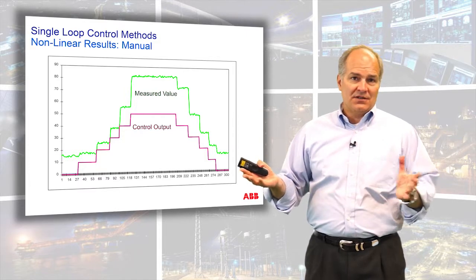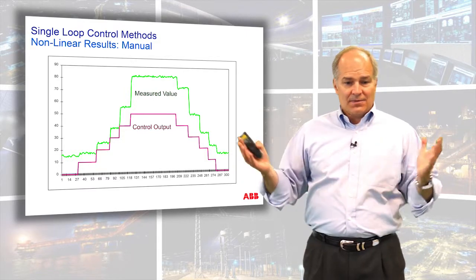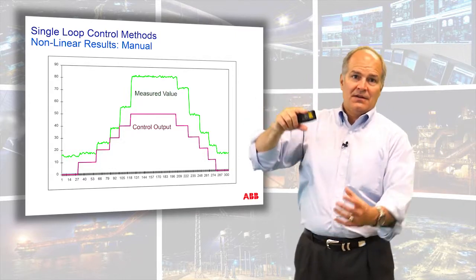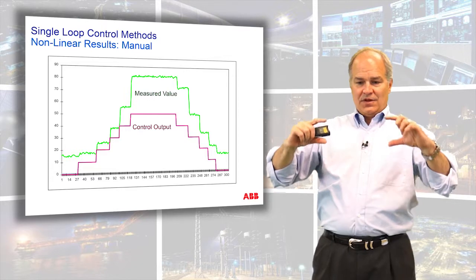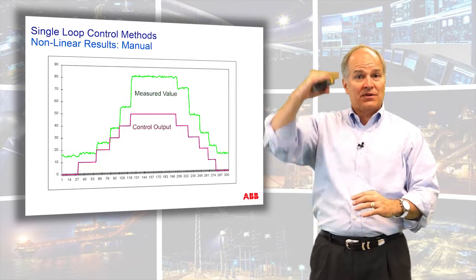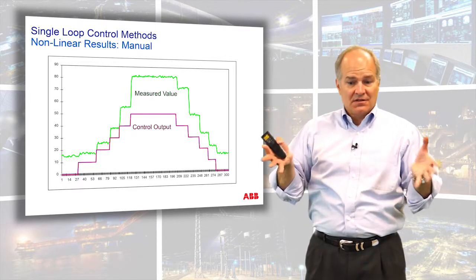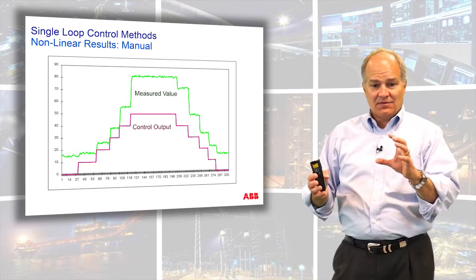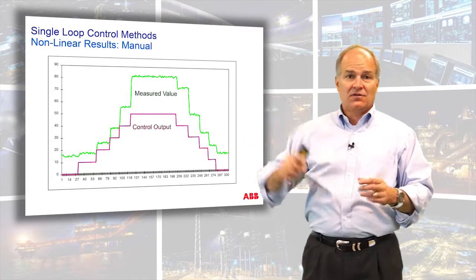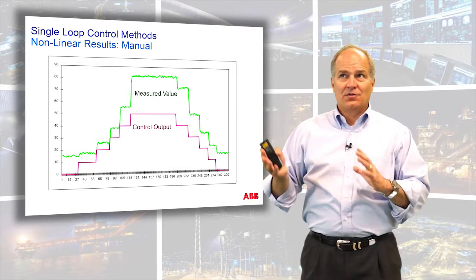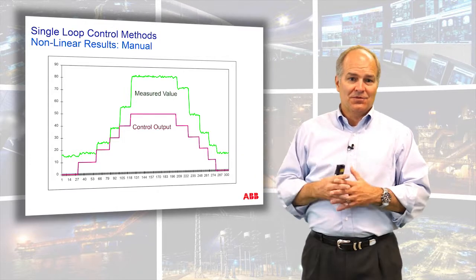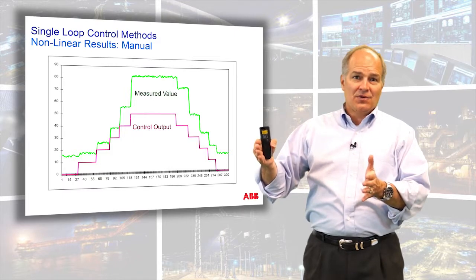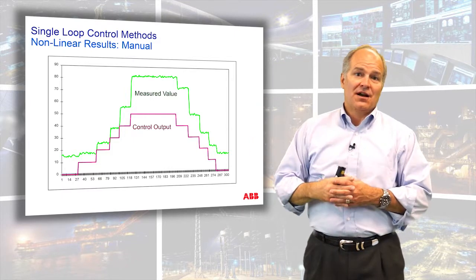There are several reasons that you can get this. For example, imagine a tank that's laying on its side, a cylinder. Well, once you get around the diameter, your process gain will change a lot depending on where the level's at. That's just a function of the process. I've seen actuators that have ranges. They have what's called an S-curve. I've heard the 10-90, 30-60 rule. That says your valve needs to operate between 30 and 60%, and you roughly have 10 to 90% of your operating range.